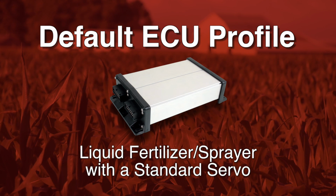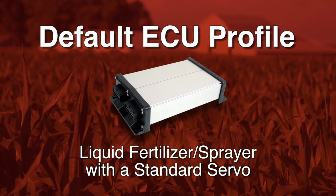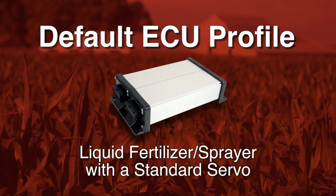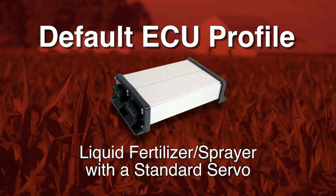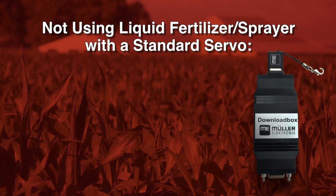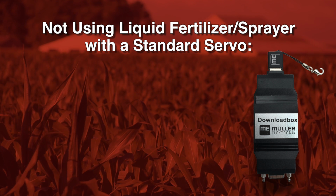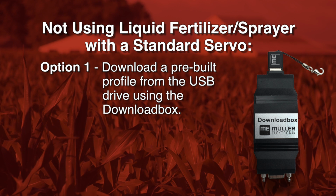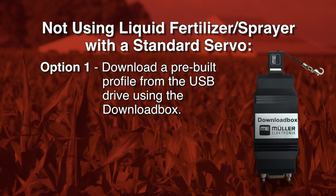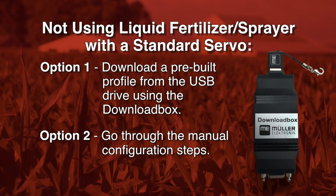The default profile for your ECU is liquid fertilizer/sprayer with a standard servo setup. If this is the setup for your bar, your profile is already loaded and you can proceed to the configuration section of this video. If the liquid fertilizer/sprayer with the standard servo is not applicable for your use, you have two options. Option 1, download a pre-built profile from the USB drive using the download box. Or option 2, go through the manual configuration steps.